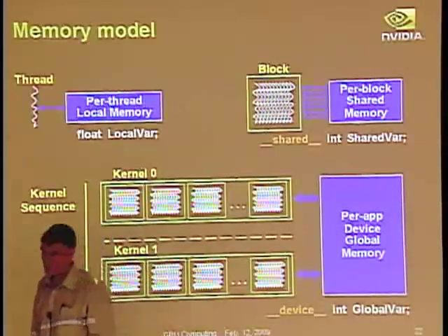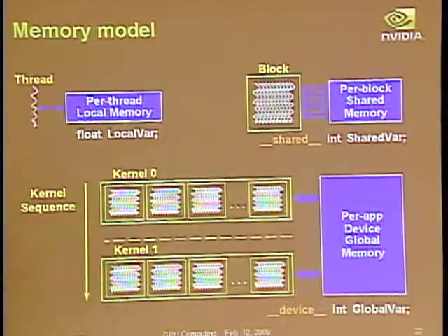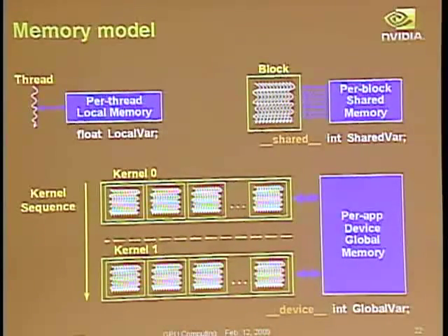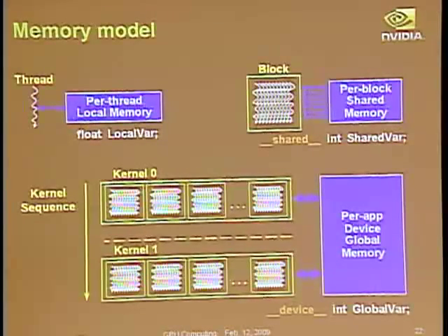Okay. You're looking puzzled. There's no memory hierarchy in terms of a cache in this memory model. Well, this is a CUDA model, right? This is not a hardware model. And in the CUDA model, this can be cached. Nothing prevents this from being cached. It's not currently cached in G80, no. Why? I mean, you even have some cache on the chip. Yeah. So what made you designers think, you know what, we're going to make the CUDA memory path uncached?